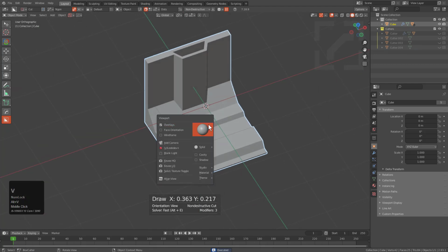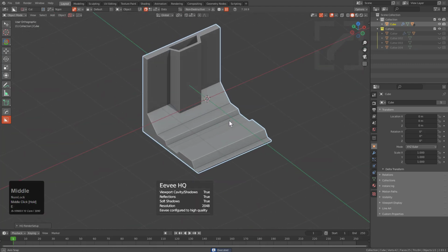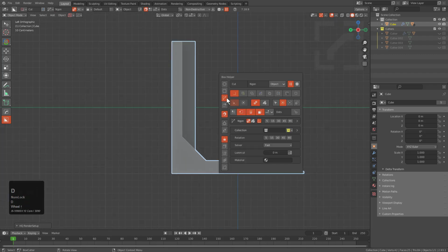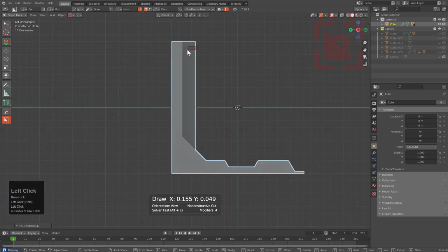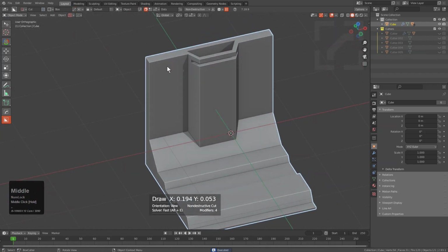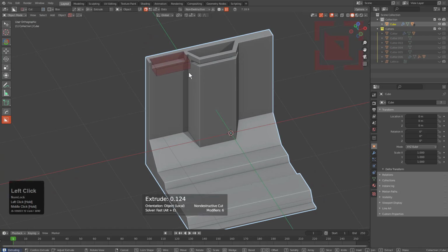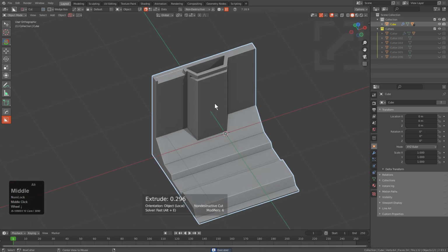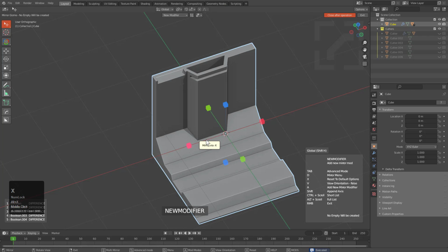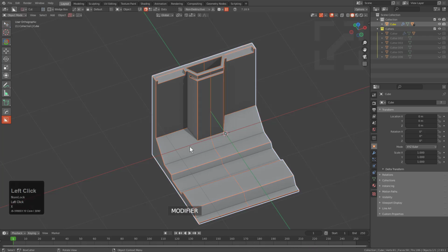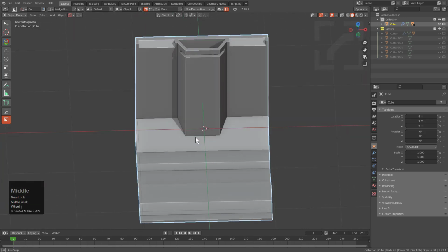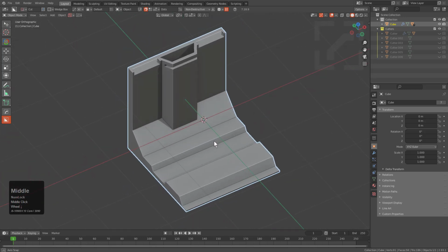From the side we can cut a few more angles in here, just letting Ngon do its thing. We can press Alt V and E in order to get the viewport looking a little bit better. We could also press D, change over to box, and perform a cut. We can also perform a cut here, but we'll press W on the way down and use Control in order to get a perfect wedge. We can press Alt X in order to mirror, and we will press X to reset the mirror to the default and simply add a mirror mod. We could have done it with new mirror as well, it didn't matter.